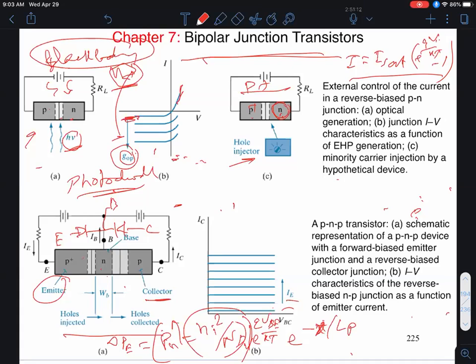But we'll ignore that for a second, because in a typical BJT, the emitter, which is p plus in this case, is assumed to be very highly doped, and most of the current then is because of injected minority carrier holes on the n side, okay? Now that expression is of course given by p-n junction theory. So the excess hole concentration, delta PE at this junction, I'm calling it delta PE because that's the excess hole carrier concentration in the base at the emitter base junction.